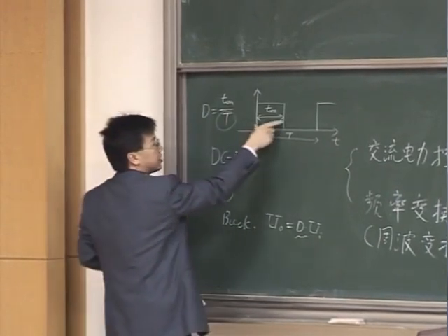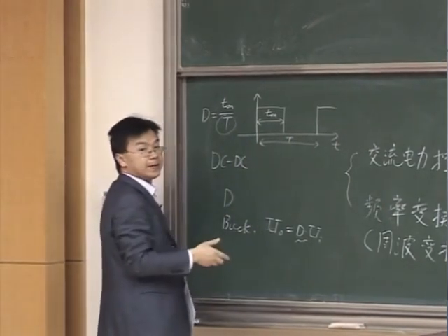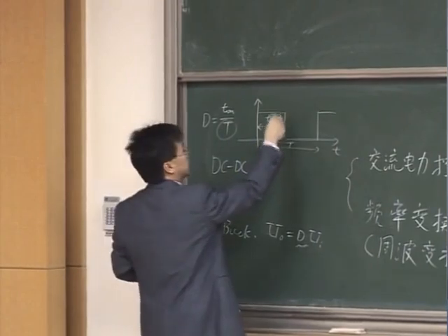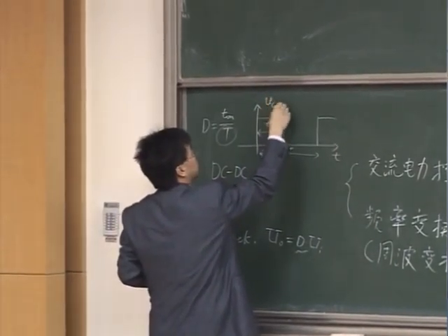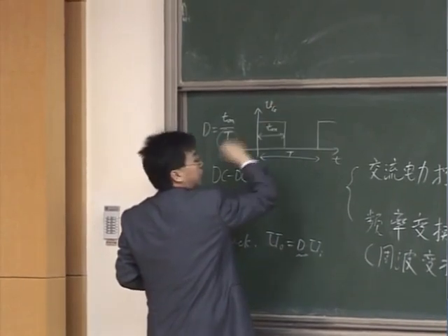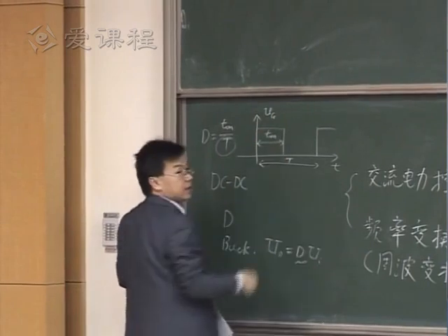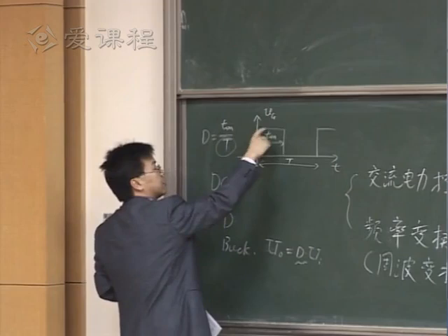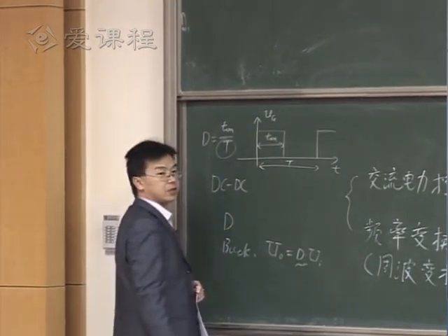And when you change T on, if you look at this waveform, let's see, if this is the gate signal for the power semiconductor switch, then if you want to turn on the switch, you send a high level gate signal to the switch.